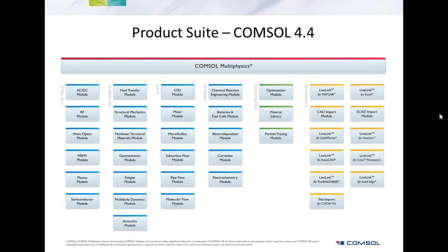Okay, thank you, Mark. Our next question, is it possible to simulate osteoporotic bone in COMSOL? Yes, it is possible. You have to obviously get a very refined model and region. For example, our material mappings are based on CT scans. Some of them are great, some of them weren't. Sometimes you need micro CT scans to get that sort of high resolution detail. So basically, you've got to get your X, Y, Z coordinates and your point valuations very close together to assess your low density points and your high density points. But yes, it is possible.